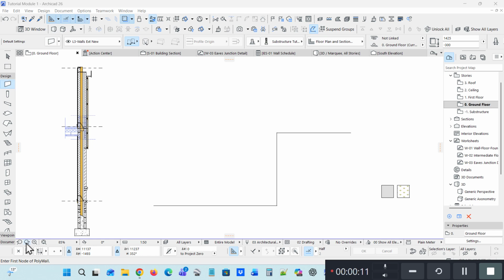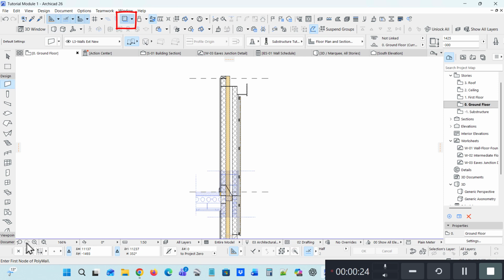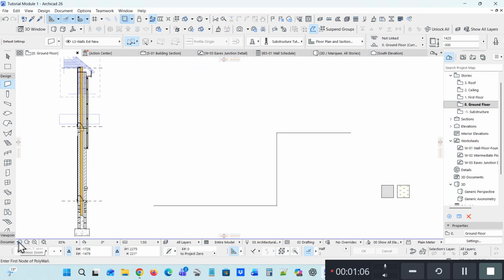Now back to my ArchiCAD model, and I've added a 2D drawing of the ground floor wall and the first floor wall, a polyline and also a mesh element, and a slab. I'll zoom into the drawing and switch on the trace button. You can see the detail level. You can add more or less.